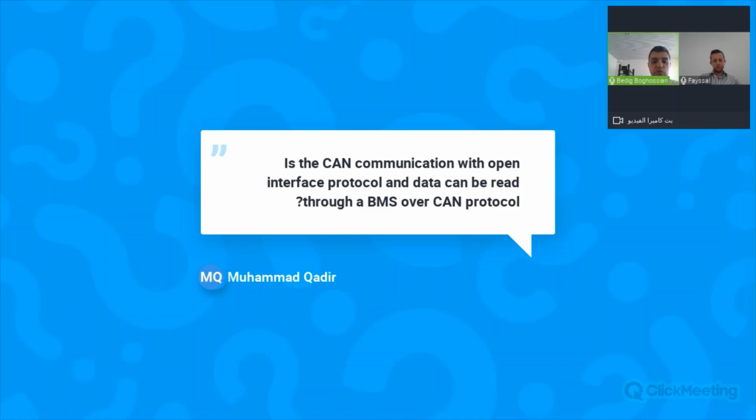J1939-75 protocol or configurable CAN, custom CAN. It's a 29-bit message ID protocol, which we call CAN2B. And as Fayssal mentioned, it all depends on your CAN master device. How does it exactly communicate? Is it 29-bit or 11-bit? The answer is yes, you can read from the genset controllers via the CAN, but that depends on the configuration.